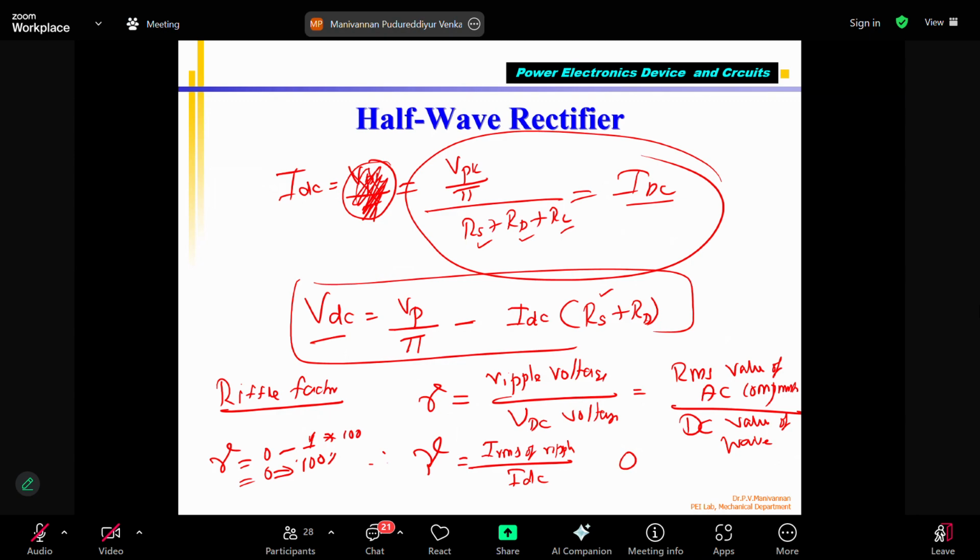Sir, one question in general, probably just a doubt. For induction motor, when we were revising, we had a doubt. In the induction motor, we use the same transformer principle to step down the voltage, but there's no separate transformer, correct? You have the stator coil, that is the primary. You apply supply and it produces a rotating magnetic field. That magnetic field goes and hits the rotor. If it is a wound rotor, a coil will be there. If it is a squirrel cage, copper conductor bars are there. They cut the magnetic field and pick up voltage, called induced voltage.